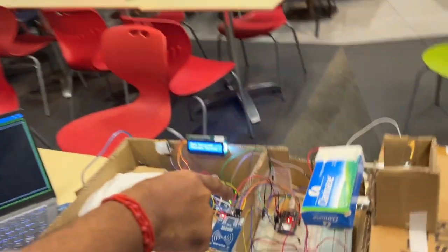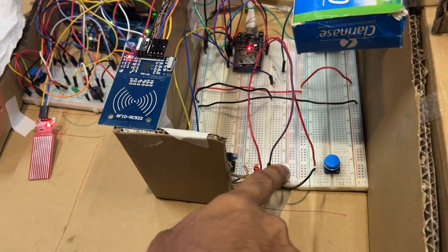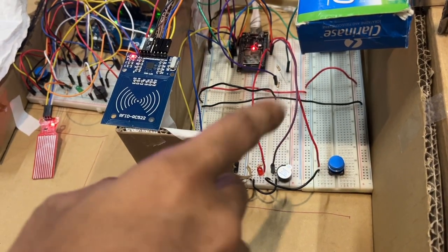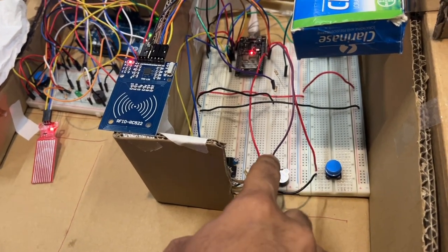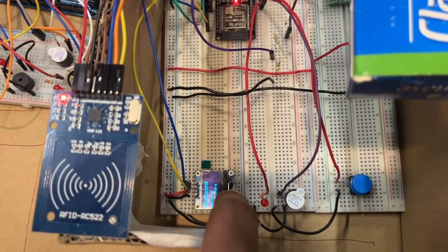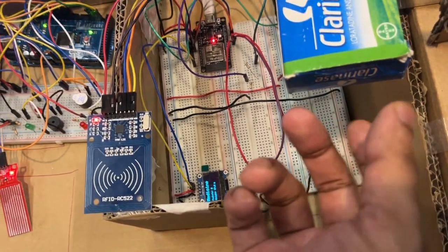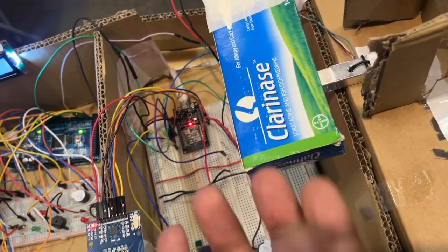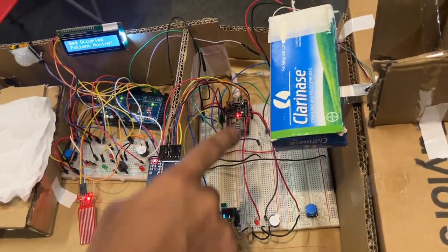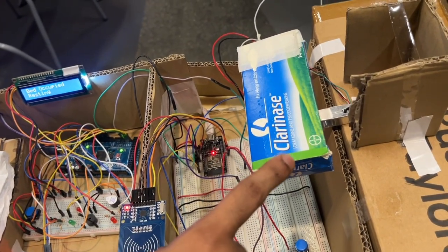So my part will be the smart inventory system for the smart hospital. I'm using an ESP32 microcontroller, and then I have a buzzer to notify when the stock gets lesser. I have an LED bulb to notify when the stock gets lesser. I'm also using an OLED, and the button here is to save the weight of the empty box. To check the weight of the inventory, I'm using an HX711 and a load cell.